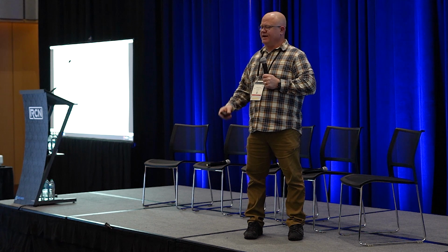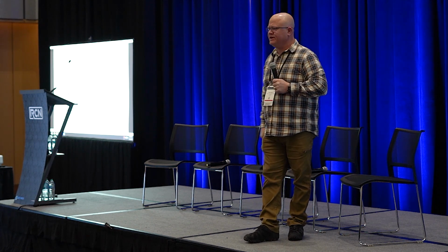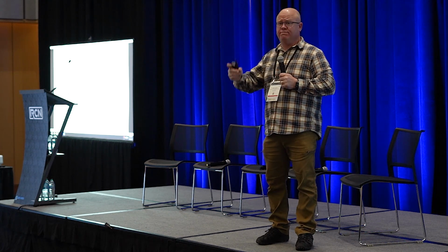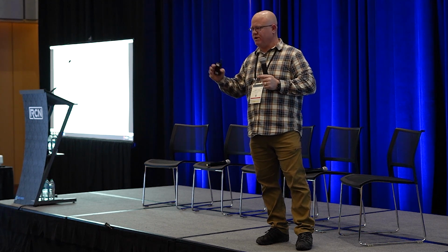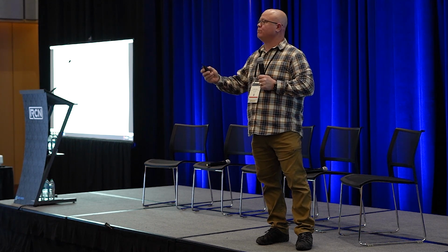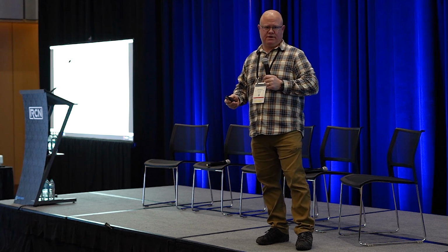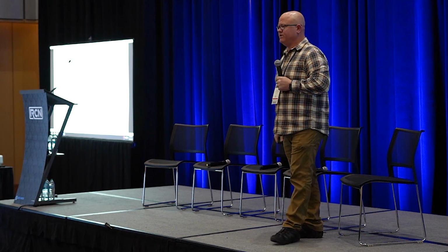You pick that RCP file, it's up there in Autodesk Docs, and you start pulling linear features, okay? I had a three-quarter mile point cloud that I had ready to show you, and I had pulled I don't know how many linear features on that thing. You can not only pull linear features, but let me back up and explain what I mean by linear features. I'm talking about curb, gutter, pavement striping, whatever you'd like to have pulled linear in that drawing.